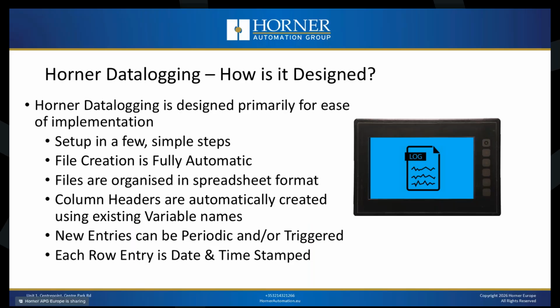How is the data logging feature designed? Horner data logging is designed primarily for ease of implementation. Setup can be done in a few simple steps. File creation is fully automatic. Files are organized in a spreadsheet format. Column headers are automatically created using existing variable names. New entries can be periodic or triggered. Each row entry is date and time stamped.